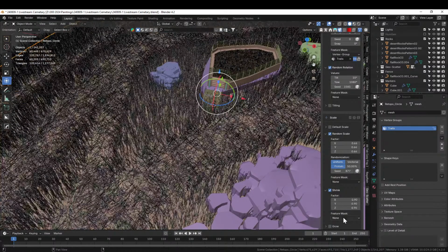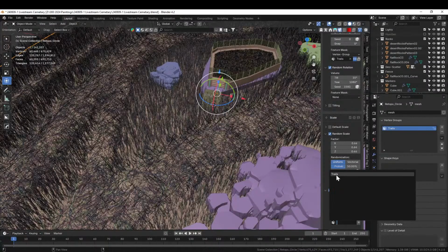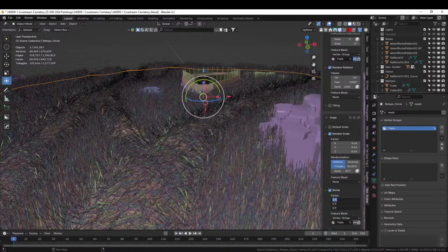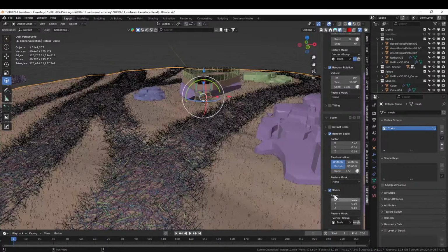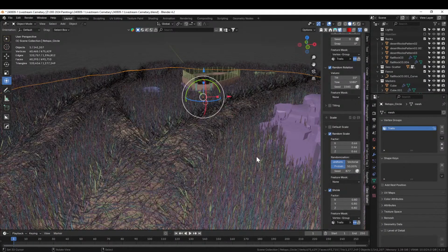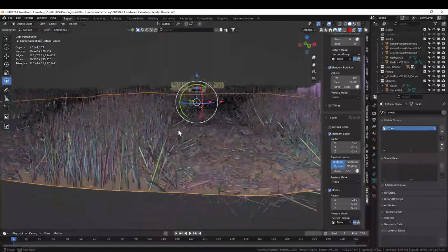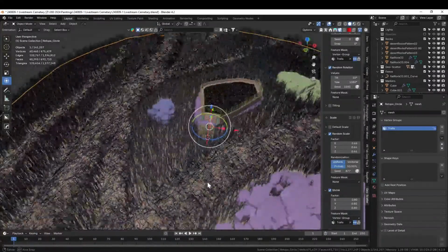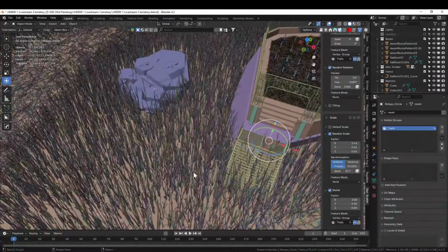And our feature mask, again, is going to be the vertex group trail. And I'm just going to see which one, 0.1. It's probably going to reverse it. Yeah, we want to reverse it. And we'll make it 0.8. Should be subtle, but just enough that it kind of gives us a little bit more evidence of those trails. Yeah. Yeah, that's cool to me.